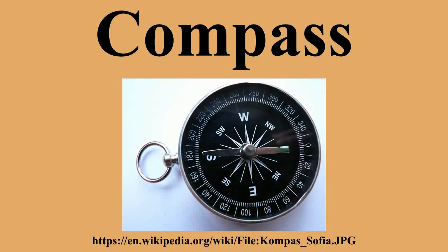Hence, they performed an additional step by measuring the compass bearing of a landmark with a known magnetic bearing. They then pointed the ship to the next compass point and measured again, graphing the results. In this way, correction tables could be created, which would be consulted when compasses were used when traveling in those locations. Mariners are concerned about very accurate measurements. However, casual users need not be concerned with differences between magnetic and true north.